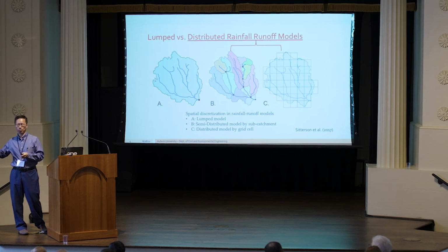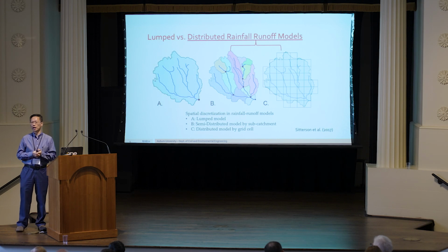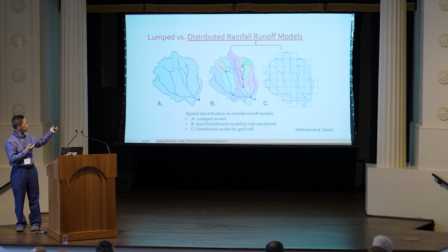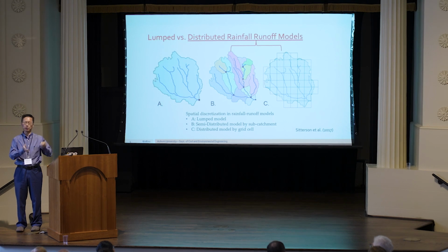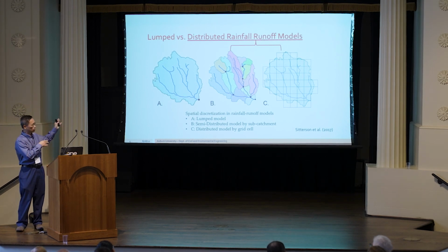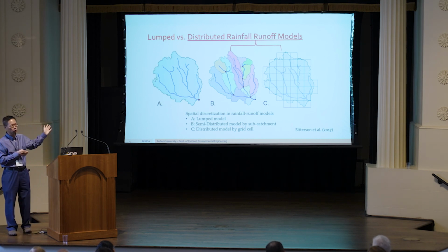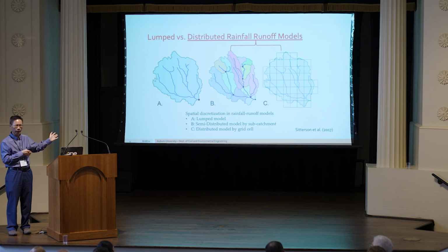And then they pop up lots of results, the peak discharge for return periods of 2 year, 10 year, 50 year, and 100 year. Behind that, they essentially apply a regression model, which was developed we don't know how many years ago. So if you make changes in that watershed, no matter what you make, StreamStats just applies that regression equation, and no matter how many times you go there to try, you get the same result.